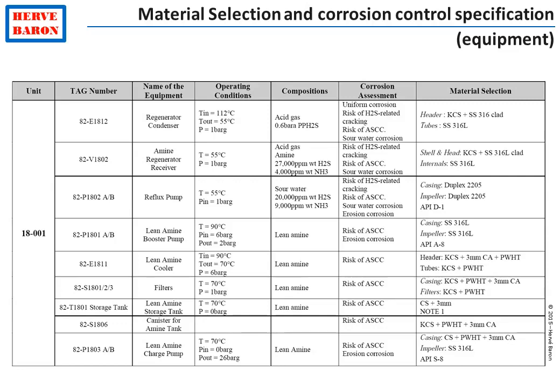In fact, corrosion cracking induced by H2S is the most common corrosion cracking phenomenon, but there are other cracking phenomena, and reference must be made to API 581, which lists all these types of corrosion cracking.